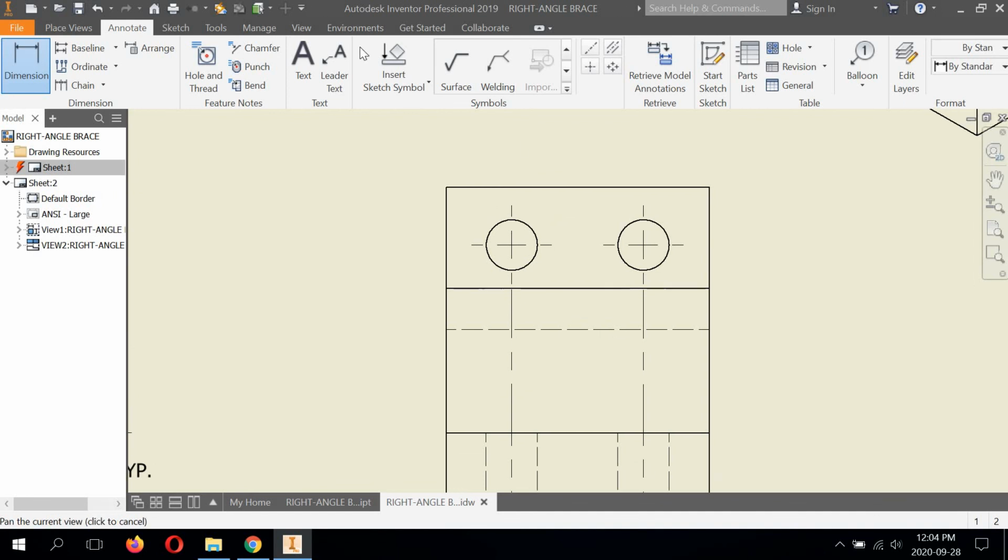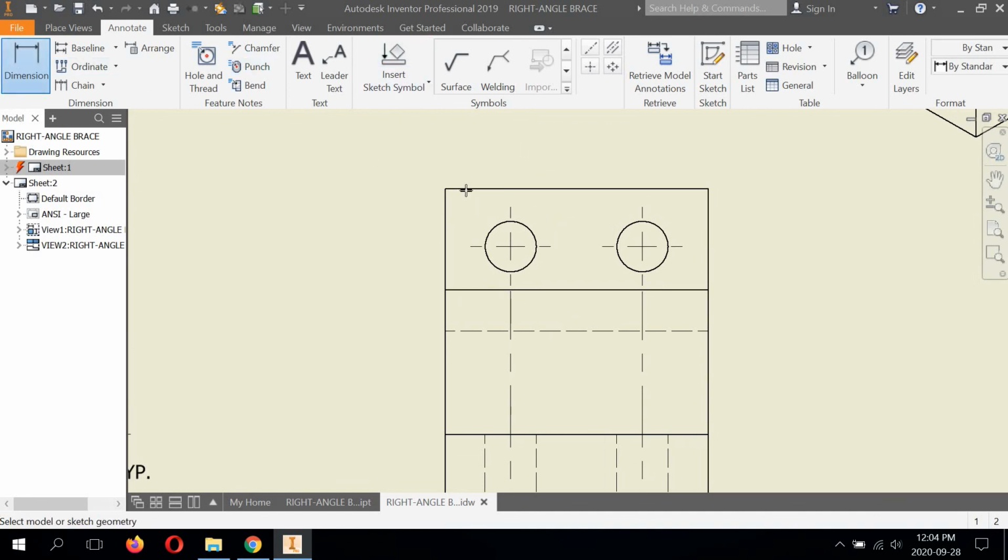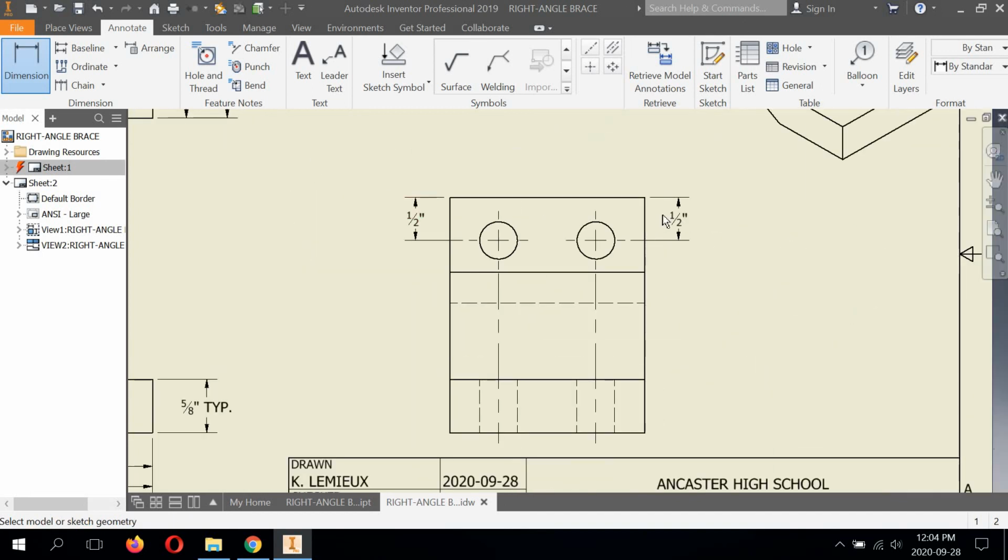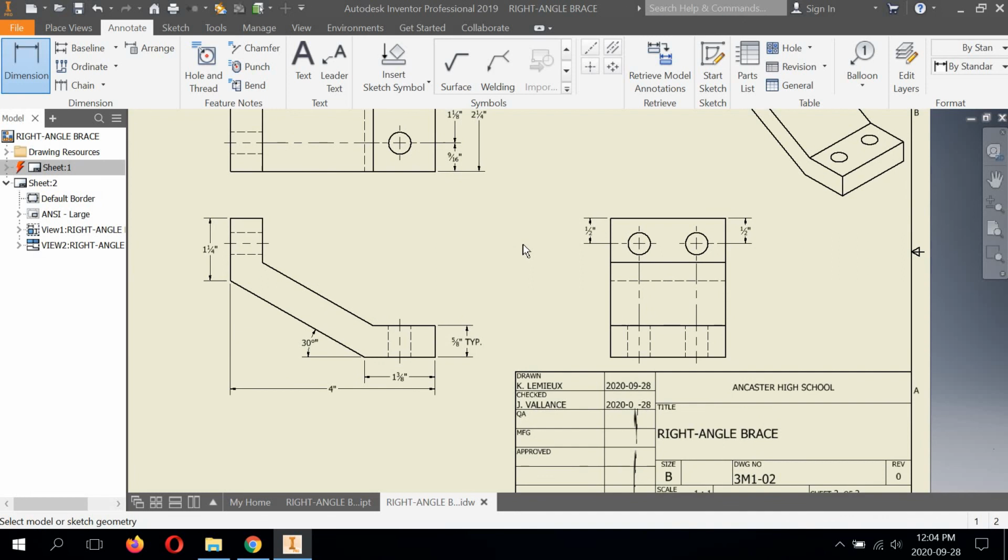So if I run this dimension twice, which I'm only going to keep one of them, to the center line, I've got it on the left side and I've got it going on the right side. This is called over dimensioning, right? I don't need this twice. But which one should I keep?